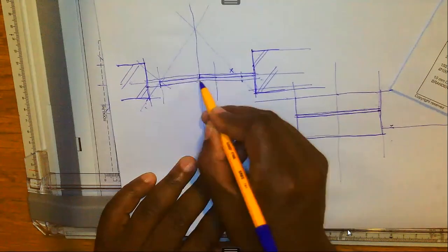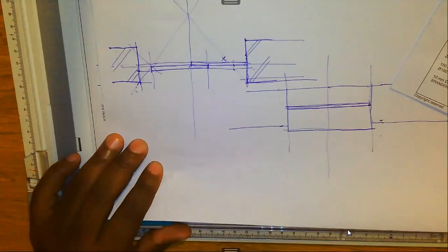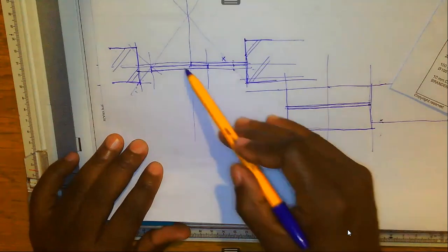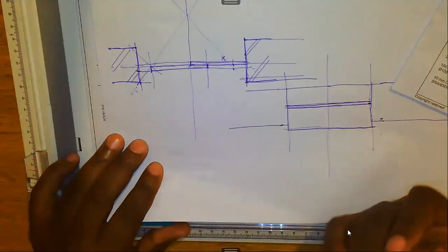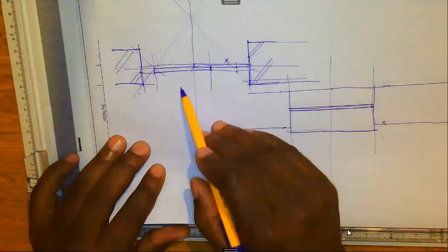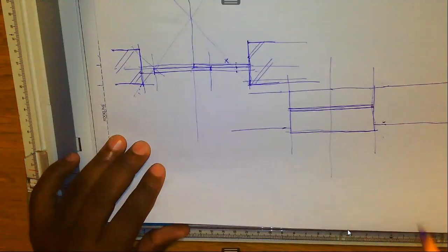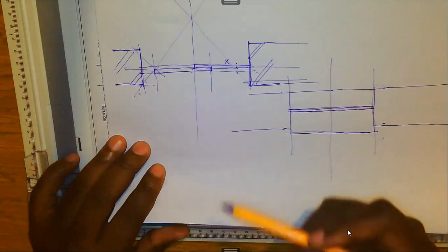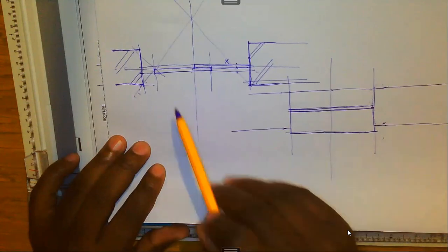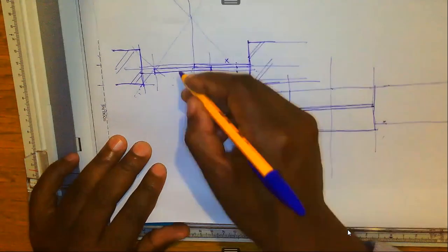Now, that is the representation of a sliding door in an opened position. You'd find that some would draw this one in a closed position. Again, it's fine, it is acceptable, but I prefer this one simply because you are able to see how the door would open and which part exactly is opening and which part is fixed. The part that is moving, normally it is denoted by a letter O like that.